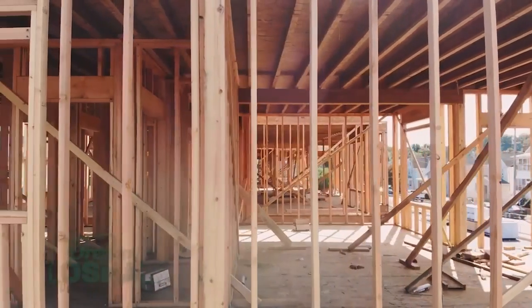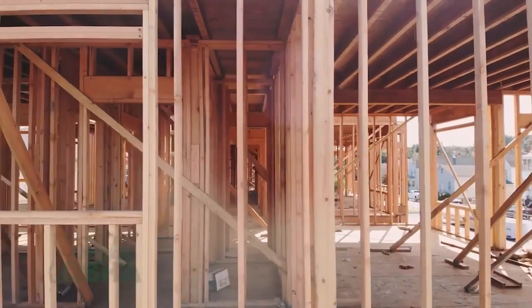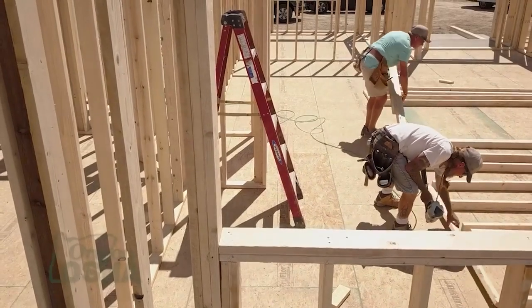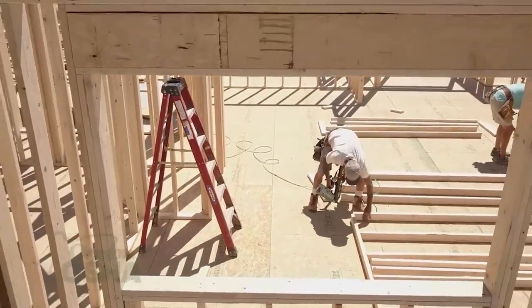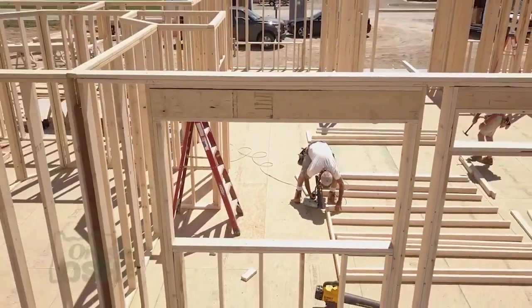As we're framing, we don't have a structure that's able to hold 5,000 pounds or 1,800 pounds. We don't have a lot of fall clearance below the people who are working up in the framing. So when we look at that, active fall protection is probably not the most effective means of providing protection for those workers. We should be looking at what we can do on the ground. How much of this can we build on the ground at that lower level and stand up complete? Can we scaffold around it?